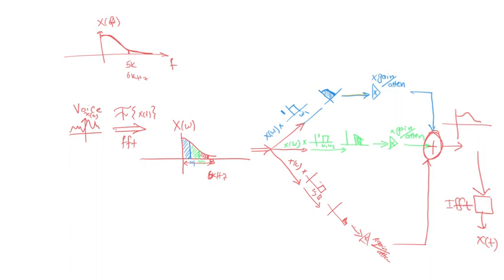Now, in terms of the circuit, when you implement the circuit, you don't need to do most of these things because in the circuit, this part, which is the filtering, is already performed by those RC filters that you will put, right? The only thing is, you know that these in frequency domain would have this representation, but the signal going through the circuit doesn't need to know that. It's a time domain signal and it flows nicely, right? We do this in the software because in the software we are trying to understand what we are doing by our hands, right? The circuit is already physically doing this effect